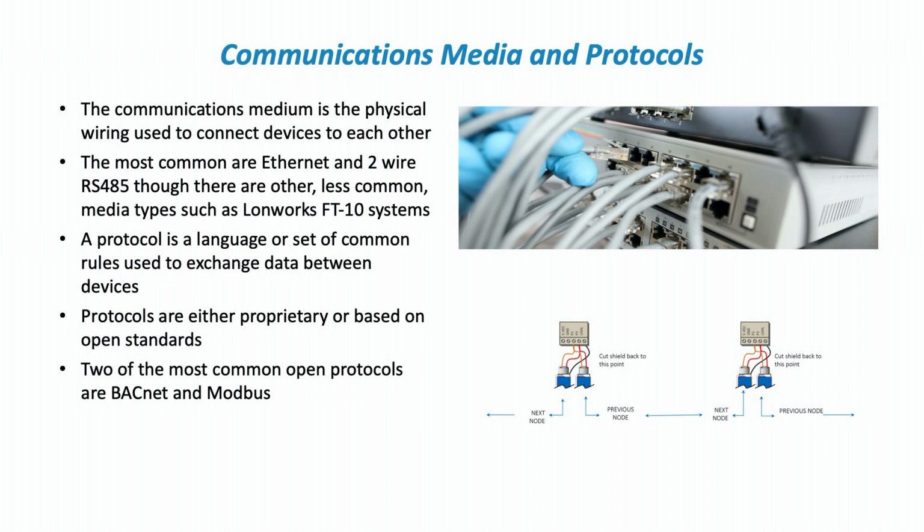Something else about RS485 and Ethernet, which they don't share with LonWorks: LonWorks was designed for building automation. Ethernet and RS485 have very broad applications outside of building automation, so they are supported elsewhere. And that means that you've obviously got a lot more people developing it, and you've got a lot lower cost for your devices because a lot more people are using it. So those are the communications media. That's the physical media that we use to send our electrical signals over.